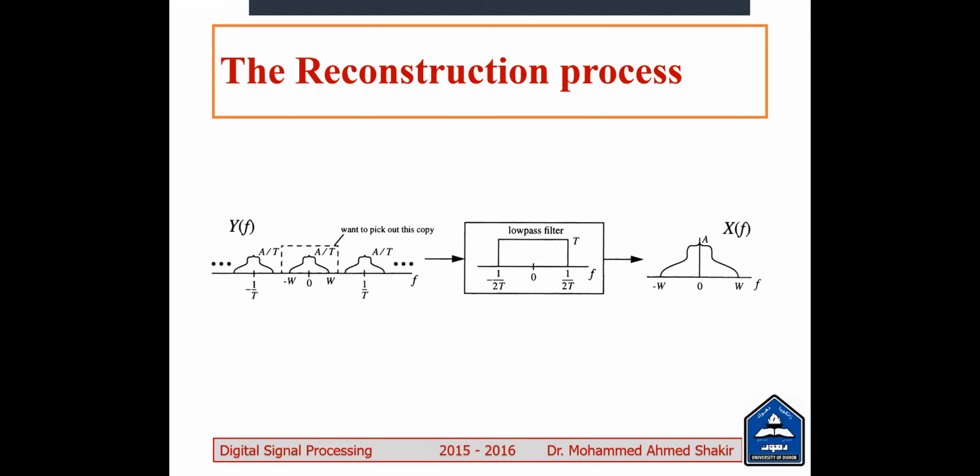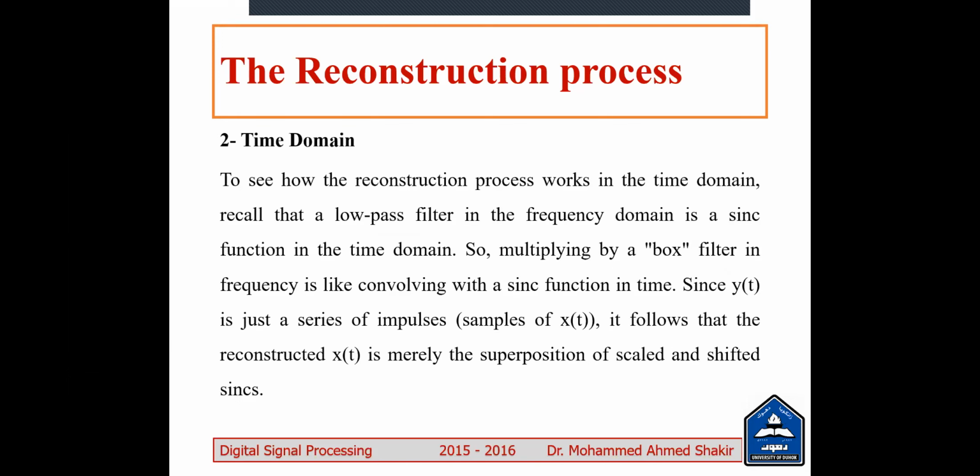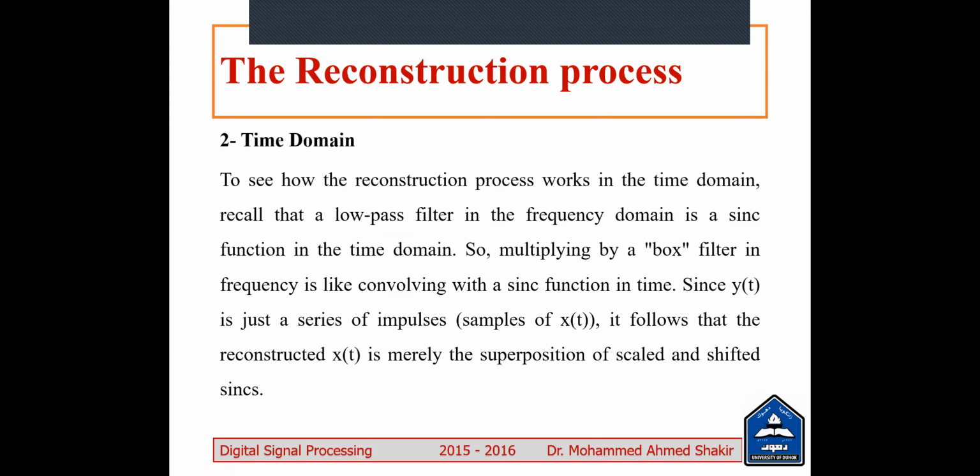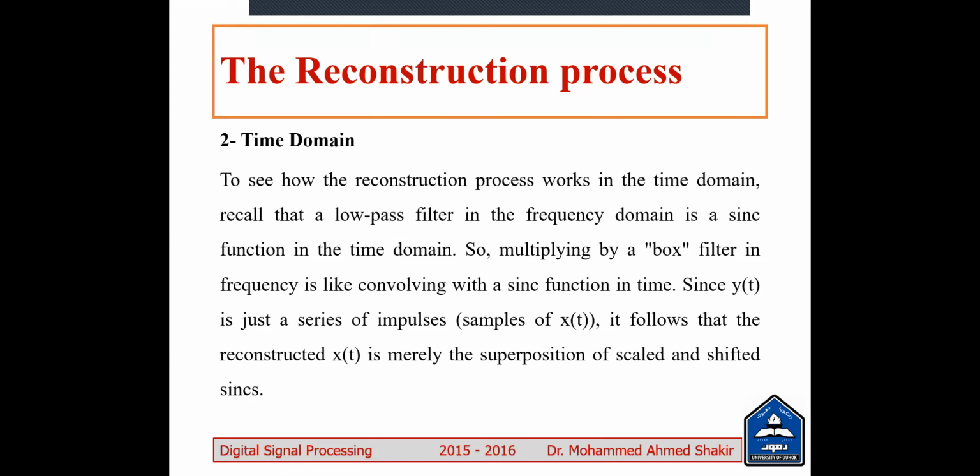So the Fourier transformation for the rect will be sinc, and the inverse for the rect of f will be a sinc function in the time domain, sinc t. We are going to use this duality to illustrate what's going on in the time domain. To see how the reconstruction process works in the time domain, recall that a low pass filter in the frequency domain is a sinc function in the time domain.